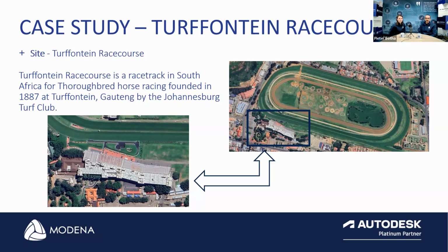What about hidden elements in ceiling voids? Can you capture that? The scanner is a line-of-sight scanner, so what you see, the scanner will see. If we have space to move into the ceiling space, for example, we can remove ceiling panels, hoist the scanner up high enough to fit into that ceiling void and then scan it. Definitely we can do that. The other alternative is a walking ceiling, which is preferred, obviously, if we have space to walk. Then we can definitely scan that much easier than a normal ceiling in a residential area, for example.